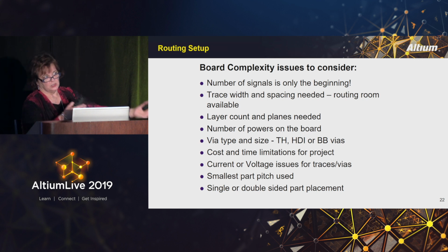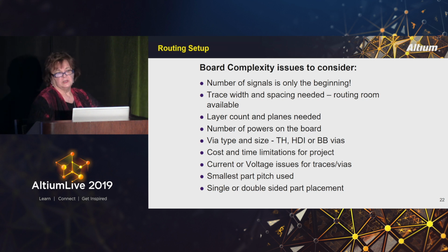If you get to a point where you've routed everything you can and you can't get any more signals out and you just go, I'm going to have to go to HDI, well, that's not efficient, and it's more expensive because you end up having multiple technologies on the board that you really didn't intend to have, and so it's not using the HDI efficiently. If you're going to put HDI microvias on the board, then put them on the board from the beginning and then use them all over the place.